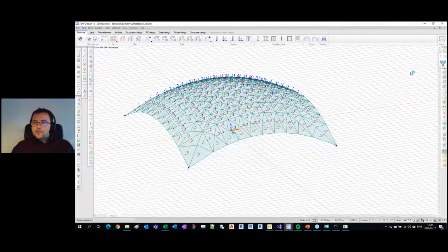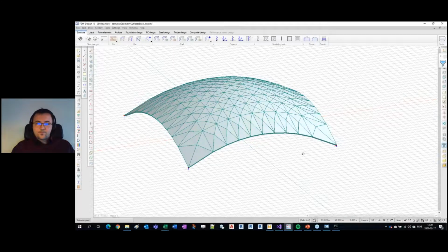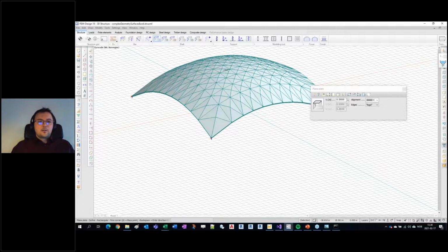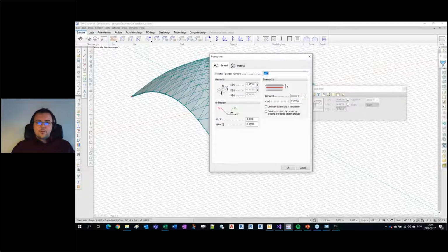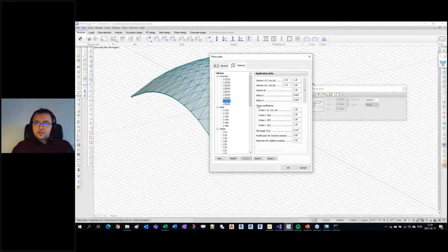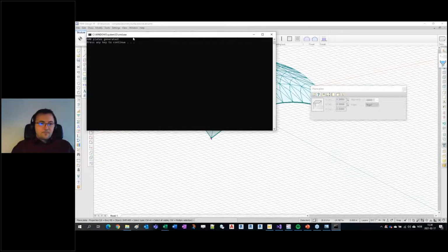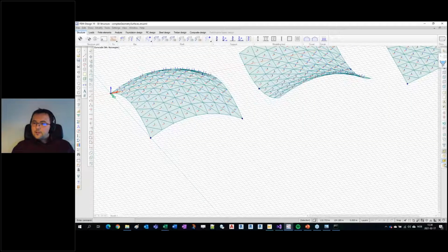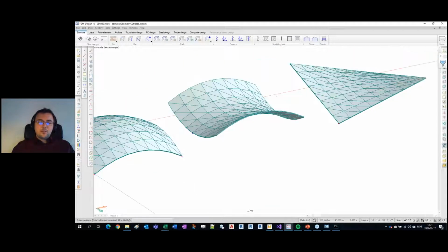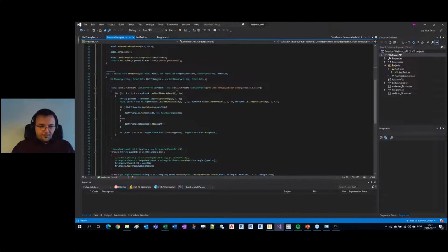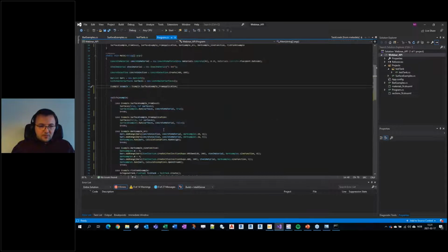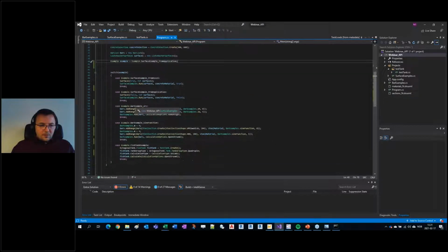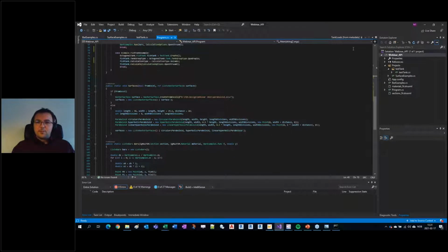So this is exactly the same as Andreas generated via Grasshopper. You can see that all the parameters are controlled from the application: thickness 35 centimeters, and automatically calculated creep and shrinkage factor. In the second example, it's about finished. The same surface is generated, but besides the so-called circular paraboloid, also generated are the hyperbolic paraboloid and the linear hyperbolic paraboloid.